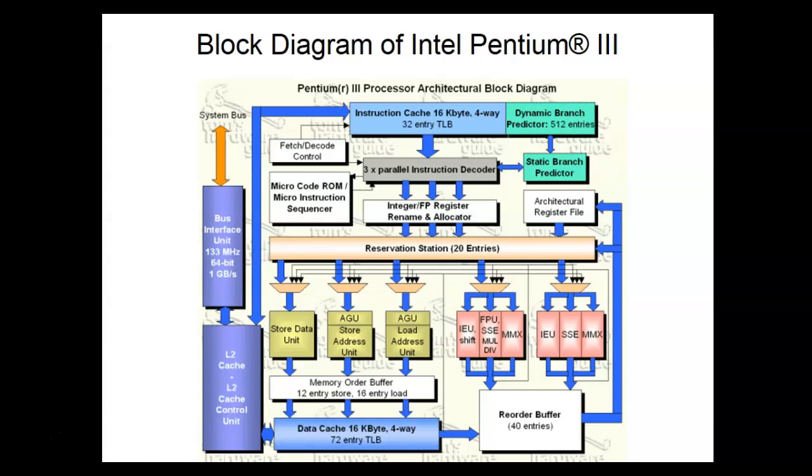What this means is the way the processor actually reads, it's called dual channel, is that it takes time to access this memory, and the type of memory it is, it's slow. So what we do now is they put like the even addresses here and the odd addresses there. So it'll read from this one, and then the next address will be where? Over here. And that doubles the speed too.